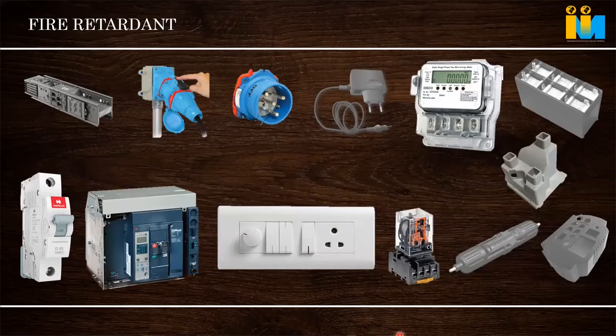How it happens is, whenever the material is overheated and about to catch fire, the additive inside the material comes out, the fumes come out and completely cover the part, so that it disengages the contact of the part with the atmospheric oxygen. Once oxygen is gone, burning stops. This is how it functions.